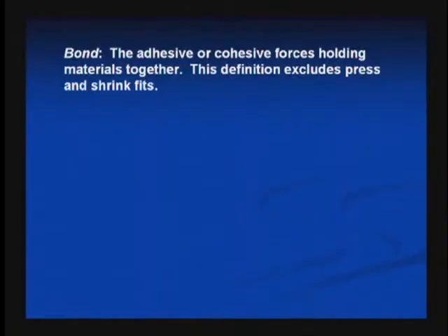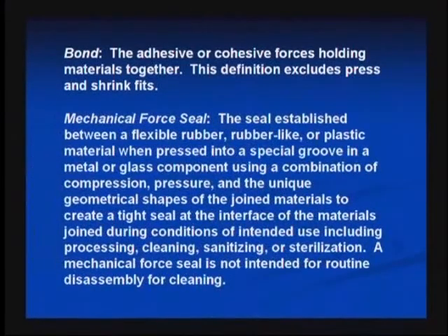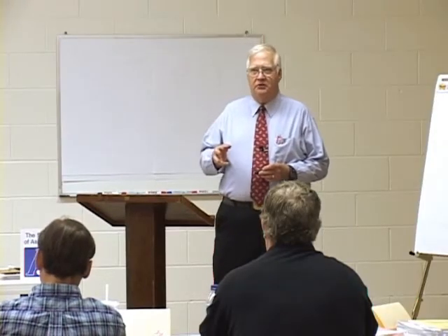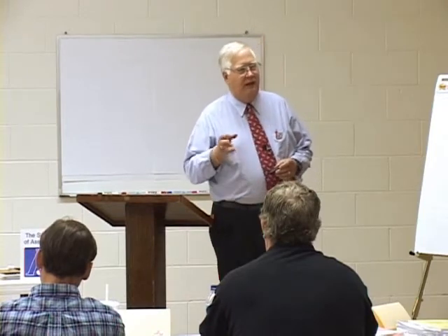Just recently, in one of the more recent updates to the Format and Style Manual, we developed this new definition for a mechanical force seal. And the mechanical force seal is a very special type of press fit that is engineered with very specific geometrical shapes of both the groove and the gasket material that are pressed into the material.